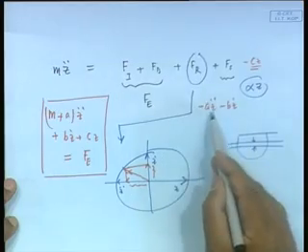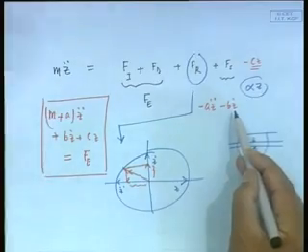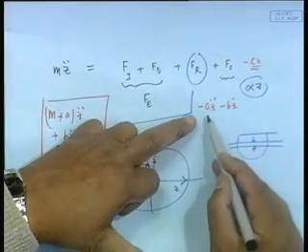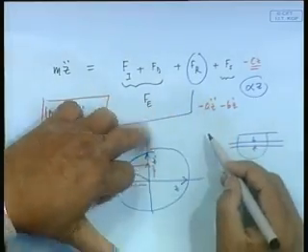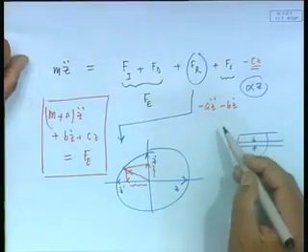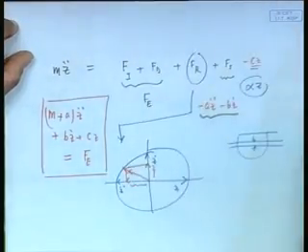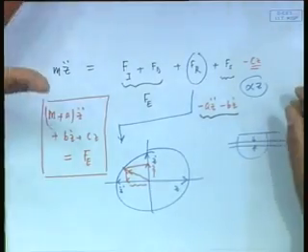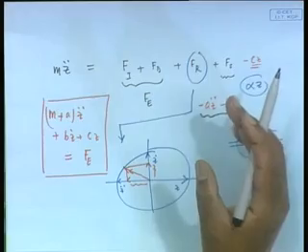See, F_r is the radiation force, which depends on acceleration and velocity, but it may also depend on the acceleration of other modes of motion. In other words, it may be a z double dot plus b z dot plus a1 phi double dot plus b1 phi dot plus a2 theta double dot plus b2 theta dot, etc. In other words, this could have arisen because of other modes of motion. If I oscillate in direction 1, it can have some pressure in the other direction. So if I add all this up, similarly F_s is what we have seen earlier,